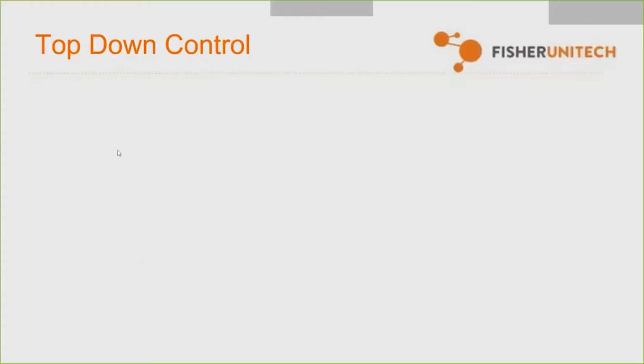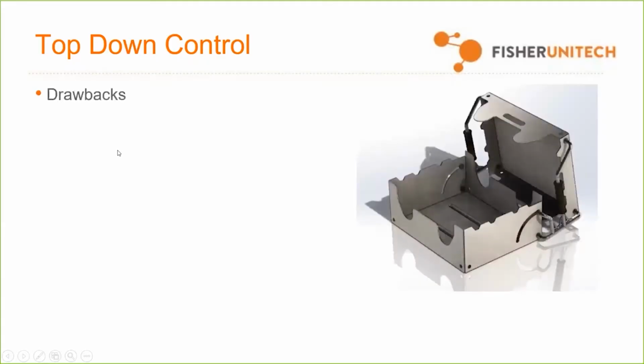Now, again, my favorite way of doing it, but it does have some drawbacks. It will affect the part directly. So if you forgot that you have this component that's actually connected to a bunch of other assemblies, then you're going to be changing the component every time you fool around with it in the custom property tab builder, and all the other assemblies are going to get updated.